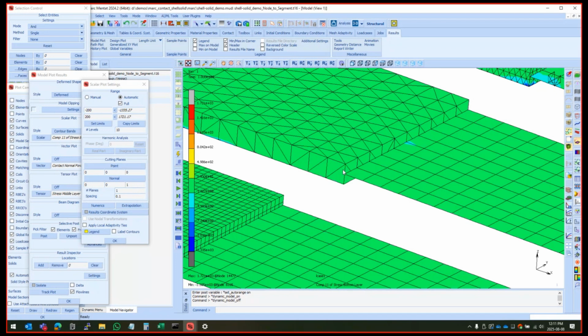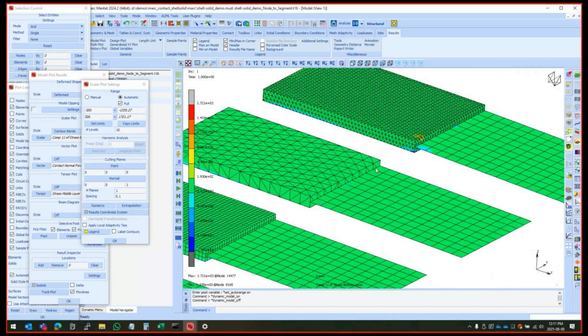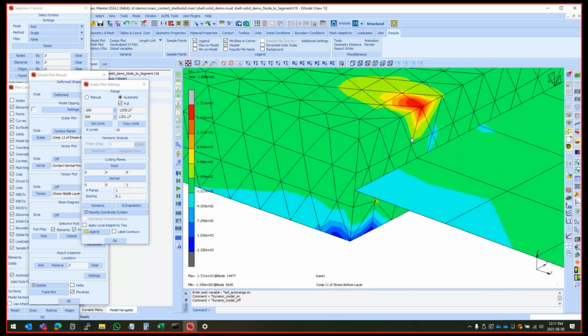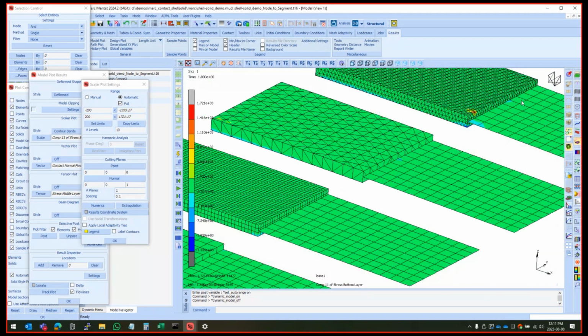I don't know whether you've seen it, but if I apply constant pressure to that face, we actually see really weird forces, some tensile, some compressive, that represents a constant stress state. Now, same happens over there. So again, we've got really high stress in some of these spots, lower stress, but it only attaches at that location to that face, or the close ones, and so on.